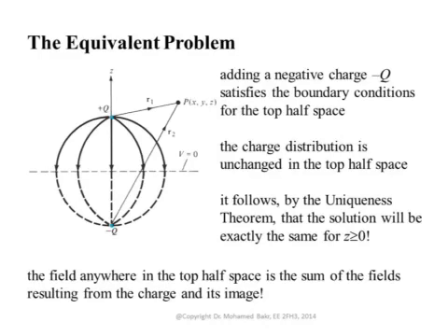Of course, once we remove the ground plane, if here we had air, here we also have air. So it's air everywhere. There is no conductor anymore. Now it's a simple problem of superposition. We can use it to calculate the field. And you can see here the field lines look something like this. They are pointing from positive to negative charge. And of course, in the original problem, we have surface charges, and the field lines starting on the positive charge all terminate on these surface charges. So this is exactly the same thing. For the top part, it is exactly the same problem.